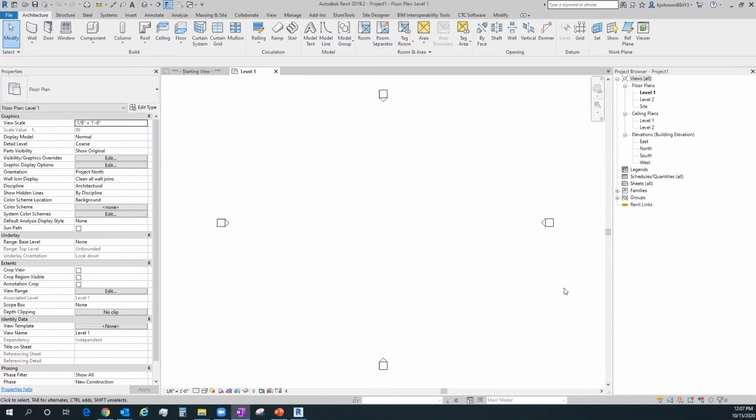Is it potentially our file, or did we crash when we just opened the file originally? So maybe we got an update from a subcontractor, or if we are the subcontractor and the prime is the architect, we get a new update from them and we put the file on our server and everything crashes. It's usually a good indicator that somebody else's file might be the one that actually has the problem. So replacement of a file or a resync of a file, and it totally blows up on me. That's probably the first area I would go check.